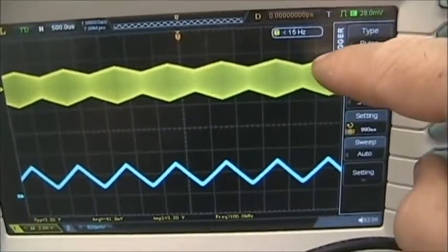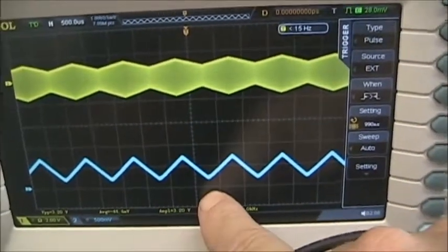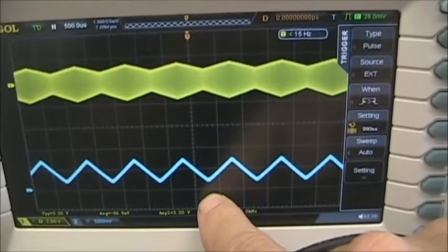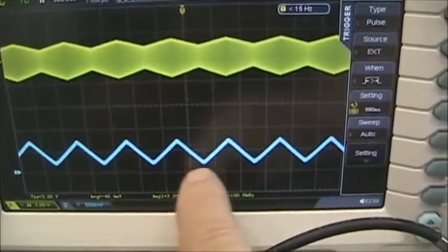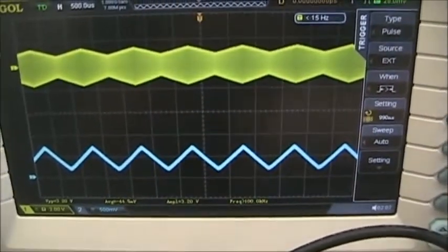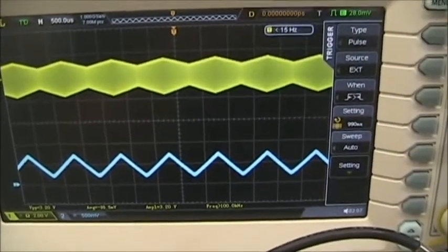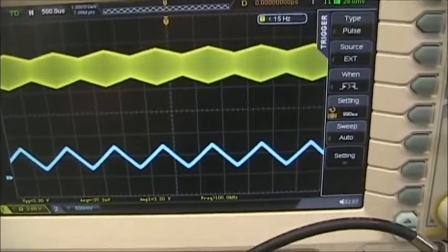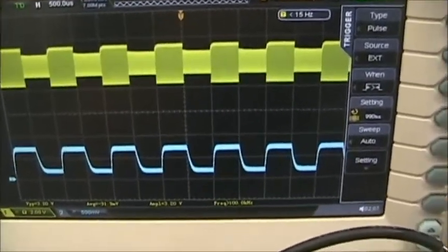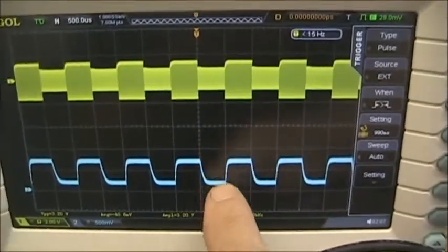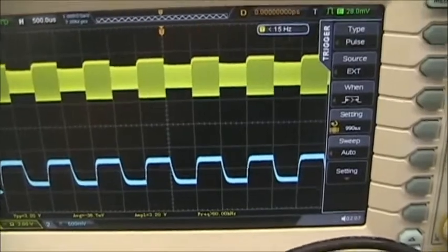So the envelope becomes our signal after the diode rectifier and filtering. And now we can run this to our audio amplifier, because this is now at 1 kilohertz, our modulation frequency, and that is essentially our diode detector demodulator. Changing to a square wave, I'll see the change also. You can see there's a little distortion on the time, but that's not going to be significant for our case.